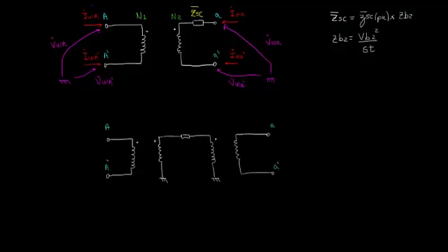The first part of the process is to consider the short circuit impedance in either a 1 voltage base or 1 turn base, like the following. The 1V in brackets notation means in a 1 voltage base. Keeping the notation, this nodal voltage can be named as V capital A 1V and the other one as V lowercase a 1V. The current flowing through the short circuit impedance is named as ISC. The currents flowing in each winding, pay attention to their direction, are named as I capital A 1V and I lowercase a 1V, and the voltage drop across the short circuit impedance is VAA in a 1 volt base.